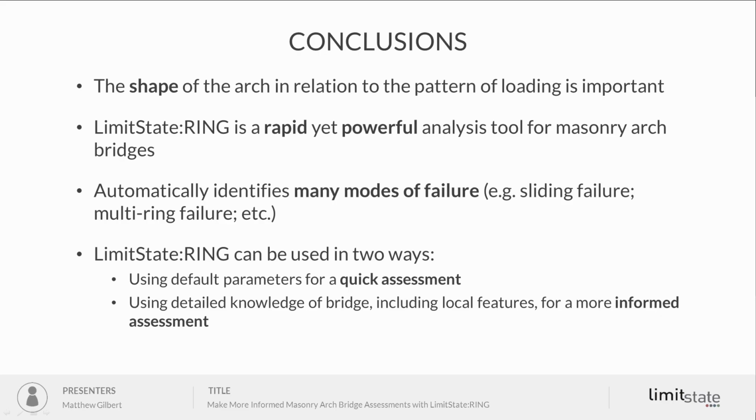Okay, so moving then on to conclusions. Just got time to bring up a few key points. First one, shape of the arch in relation to the pattern of loading is important. If you try the software, you can see that very clearly, and any sensible masonry arch analysis program should tell you the same.